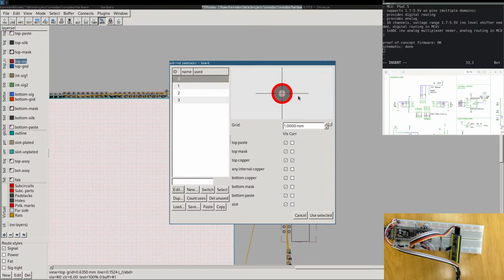For example, when you have a BGA, you have signals going under the BGA somewhere, often through a via somewhere else. You cannot probe the BGA ball, which is under the chip, but you can probe at least the via. If it's tinted, so covered with solder mask, you don't have access to it.